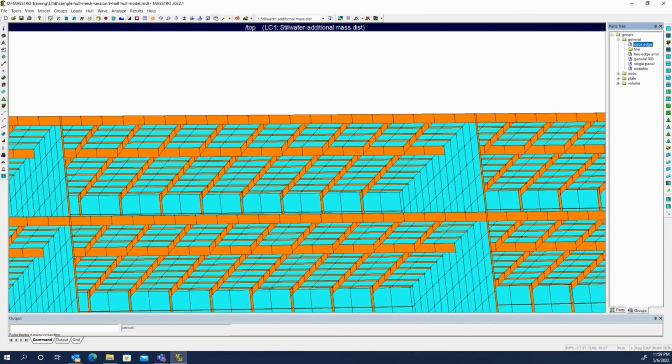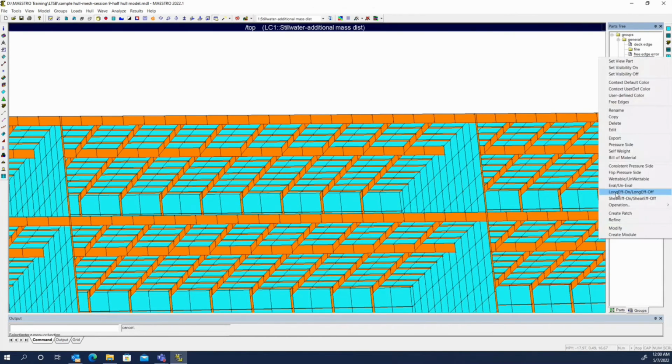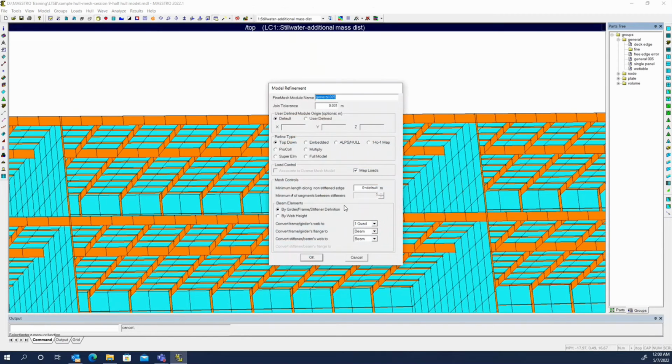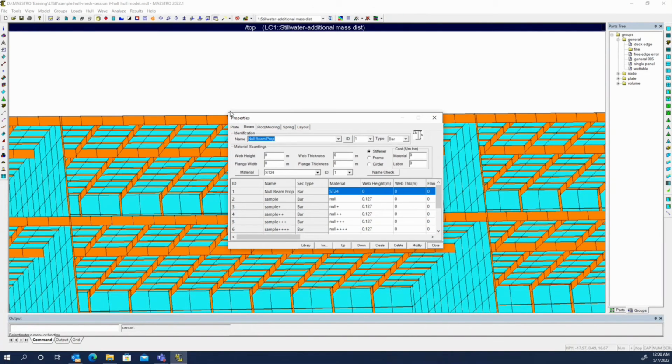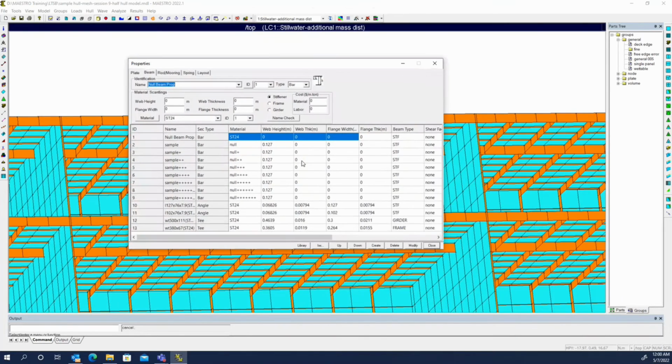That'll be enough for the demo. So this one will use web height. Now we know our girders were 500 millimeters, although the web height is actually a little bit less than that. If you look up the actual beam sizes from a properties table, we can see that our 500 millimeter girder is actually about 464, and our 380 frame is only about 360.